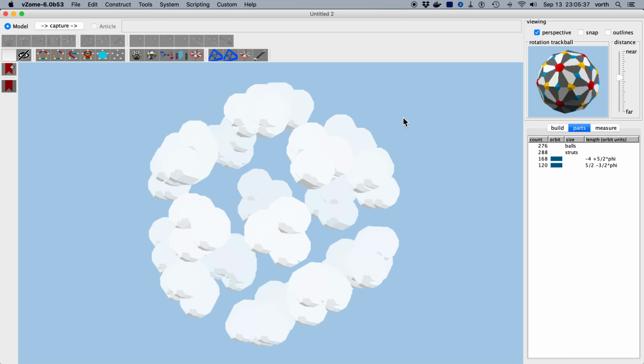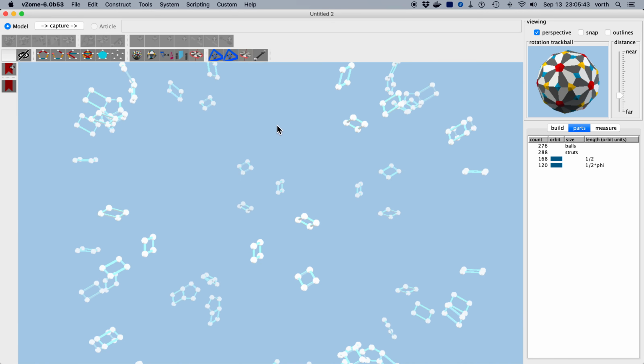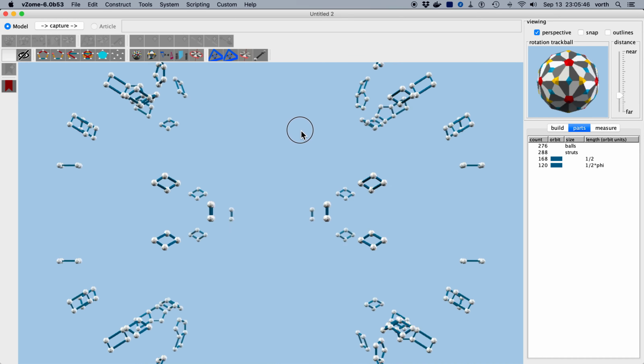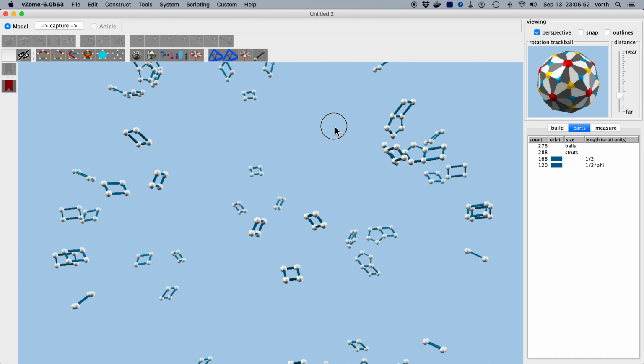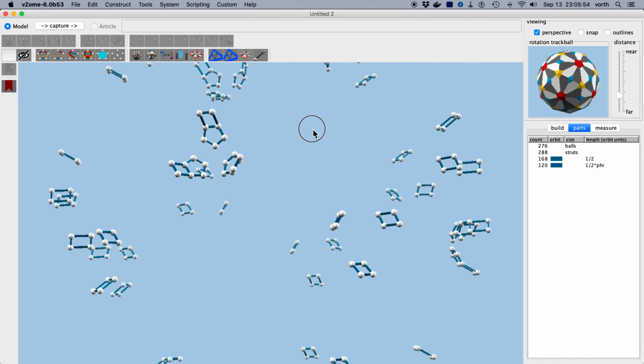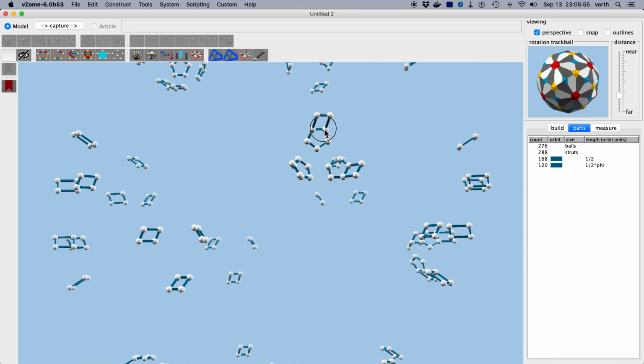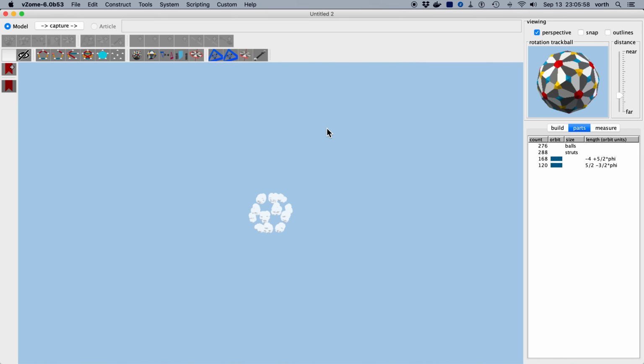What's happening, we can see if we select everything and enlarge it a few times. What you can see is that the tool has highlighted or outlined all of the panels that are problematic in terms of the constraints of the STL file. So we need to get rid of some panels or add some panels or something.